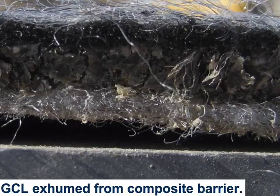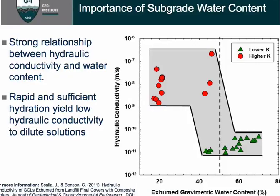So we took these samples back to the lab, and in the lab we ran hydraulic conductivity tests. We measured the water content of the GCLs. We looked at the water content of the subgrade. And what we found, here is a plot of hydraulic conductivity versus the exhumed gravimetric water content of the bentonite component of the GCL. We found that the subgrade water content and the GCL water content are very important relative to the hydraulic conductivity.